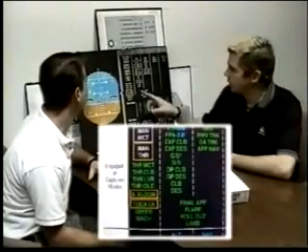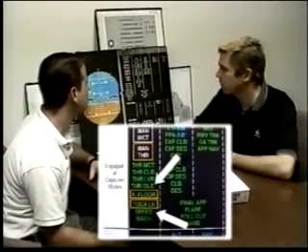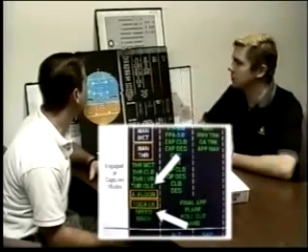Descent? Descent's the only one that's going to trick you up there, and it uses thrust idle or speed, depending on what phase of descent it's in there. It's the only one. Every other one is associated specifically with one auto thrust mode.